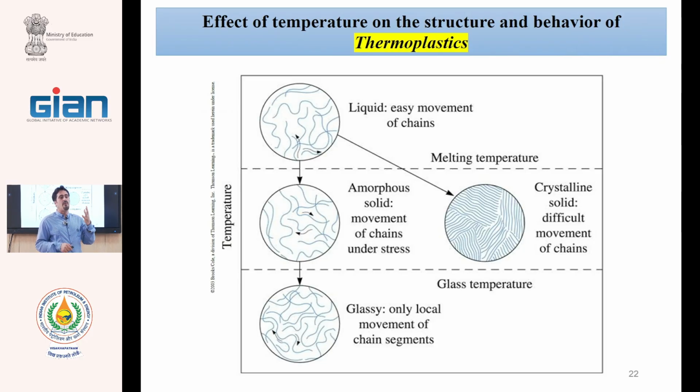With an increase of 5 centigrade, maybe the flux increases 3 times, and rejection will reduce. Therefore, in testing gas separation membranes, we should control the temperature. Our test equipment should be inside an oven or immersed in water, as discussed in the afternoon.